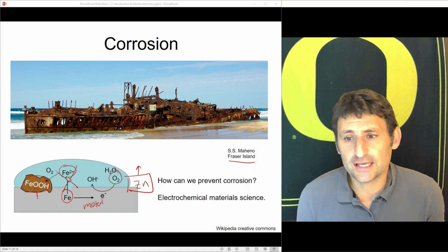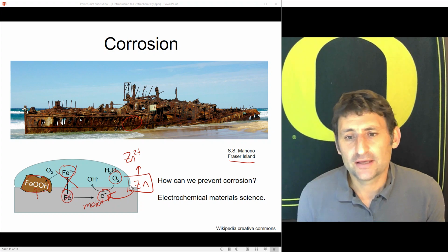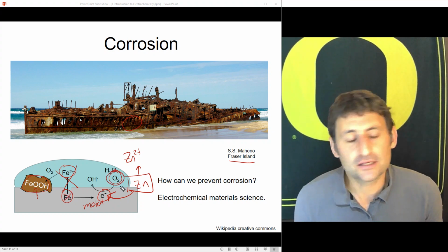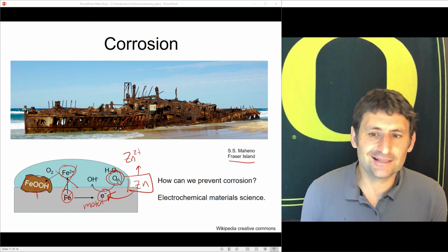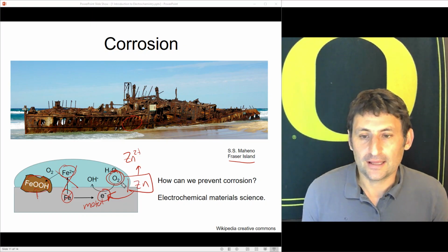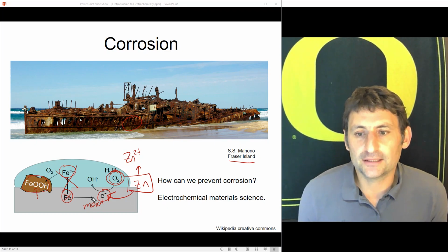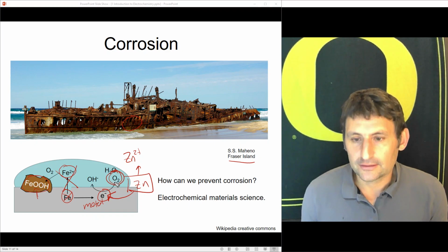The oxygen is what's taking the electrons from iron to make the rust. Now, if zinc is much easier to oxidize than iron, I can take those electrons from zinc instead of taking them from iron because it's easier to get them from zinc, and I can consume all the oxygen. So basically the zinc is getting oxidized preferentially and consuming all the oxygen. Even though the zinc is only in one spot, the electrons can move everywhere in the metal.